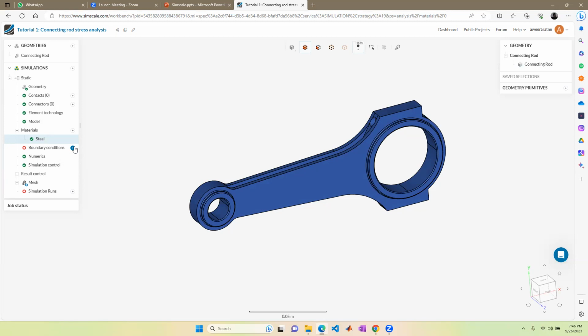And there are no safeguards provided by SimScale, and even in ANSYS, they don't provide any safeguards to prevent us from modeling a scenario which isn't what we really want to study. So setting up the boundary conditions in the appropriate manner is a skill you need to gain through practice and through reading papers of what others have done.